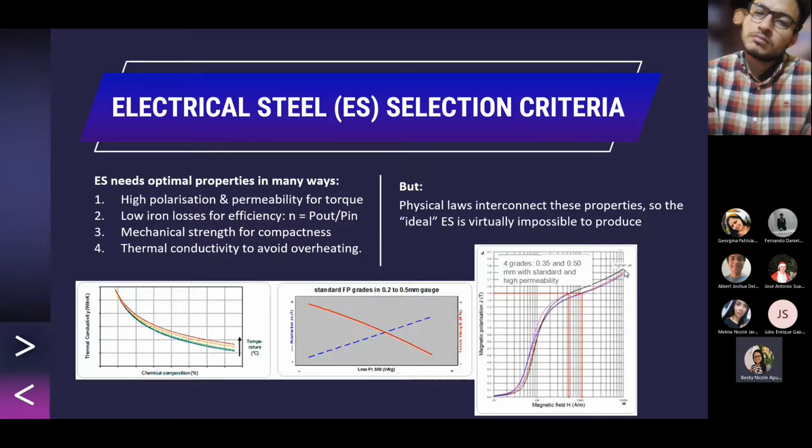If you find yourself in a situation where, for example, for the torque I need in my motor I want to be at a 1.5 Tesla working point, with the graph above you will need less magnetization current.